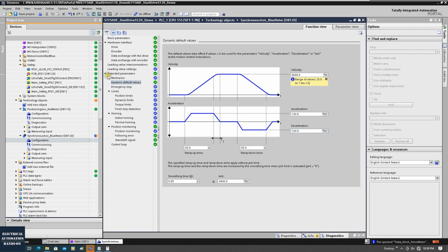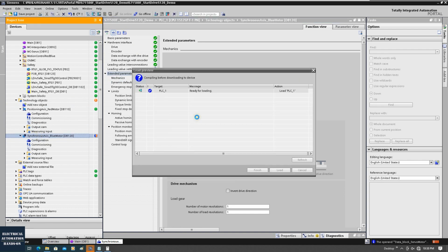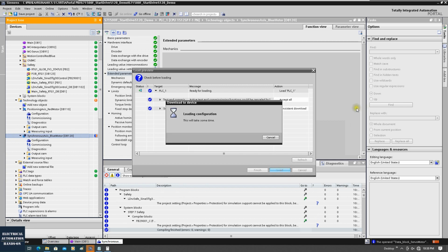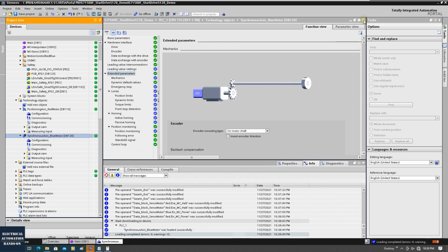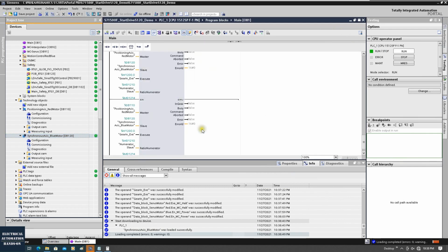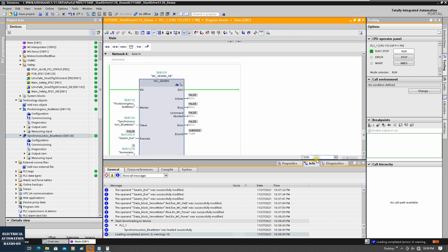Okay, and now download. This is used to verify if this GearIn here is set to minus, so that the acceleration and deceleration actually come from this slave, that dynamic acceleration deceleration value. Okay, now let's run again.